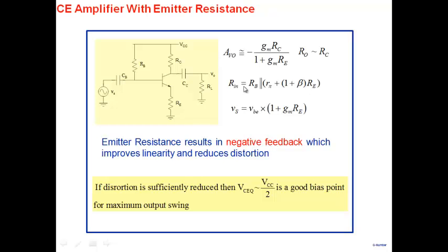It brings benefits of higher input resistance. You can apply larger input voltage here. And also, we have not discussed here, if you calculate the frequency response, the bandwidth of this particular amplifier improves. So negative feedback introduced here brings a lot of benefits. At the expense of, whenever you introduce negative feedback, you're exchanging a set of good qualities, a set of good things that happen, against something else that you sacrifice. Usually it is the gain. You end up sacrificing the gain.